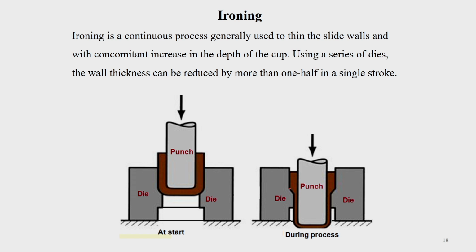Maybe when you see that on this die itself, it may initially be like this, but somewhere below that you will find the die shape is like that, there is provision for thinning. In that case metal will flow along here, and till the complete punch traverses downwards, the full extent, it will just keep on. But you have to be very careful, otherwise sometimes the metal may still not be enough. So, that punch stroke adjustment you have to do properly.